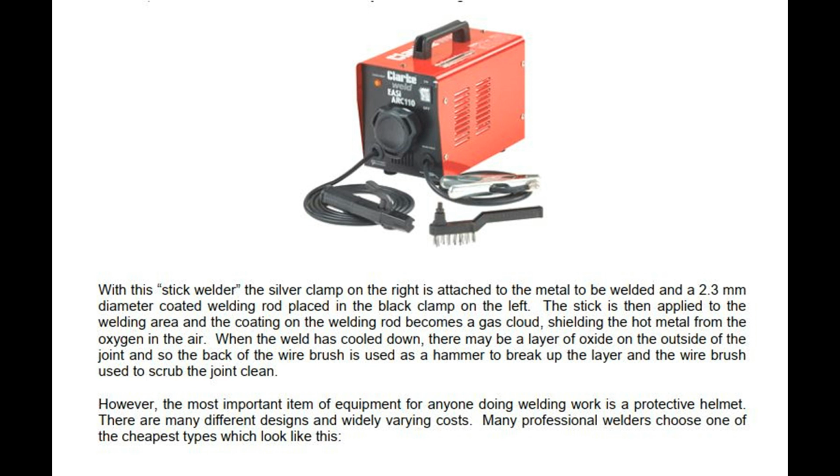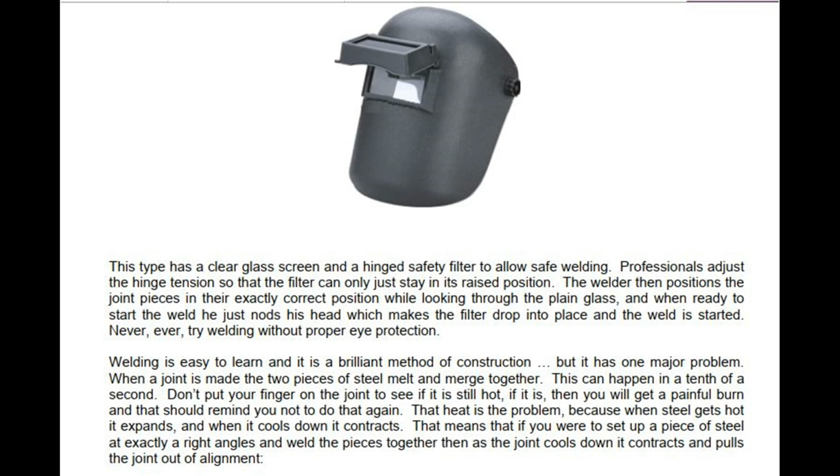However, the most important item of equipment for anyone doing welding work is a protective helmet. There are many different designs and widely varying costs. Many professional welders choose one of the cheapest types, which look like this. This type has a clear glass screen and a hinged safety filter to allow safe welding. Professionals adjust the hinge tension so that the filter can only just stay in its raised position.